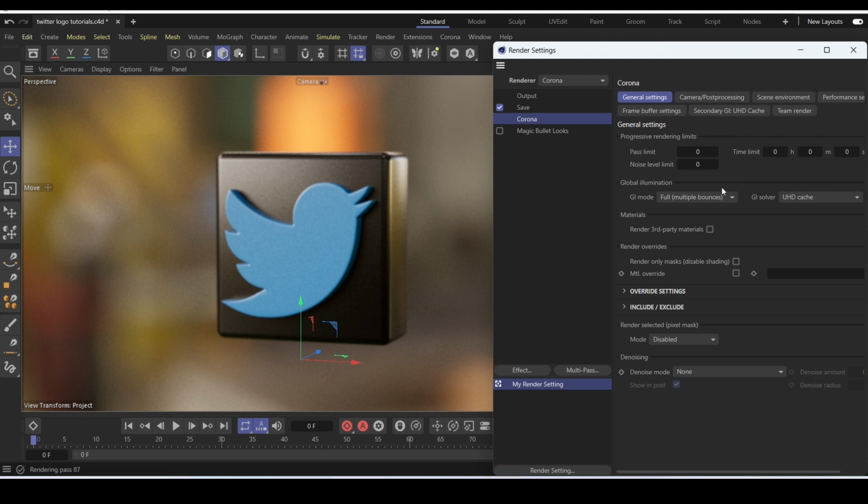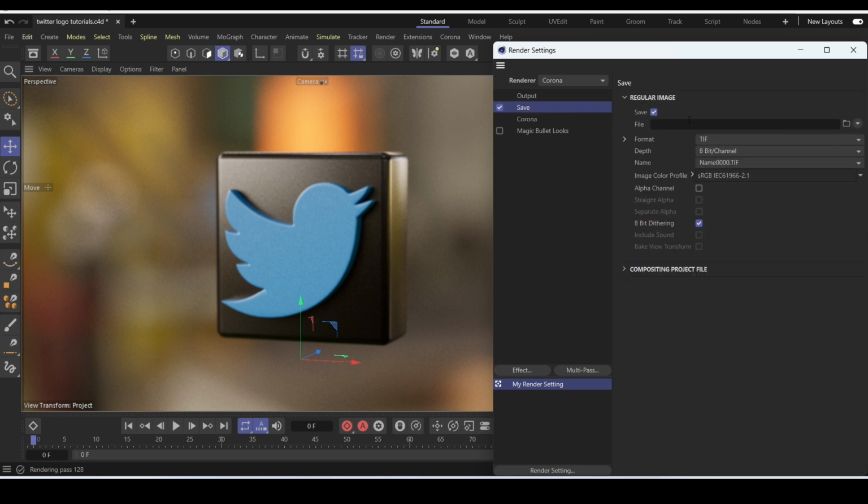So just for this tutorial, set it to like 15, maybe 10, depending on your laptop. We can go all crazy. 10. Set your denoising mode to Intel CPU, unless you know you have a strong graphics card. Then use NVIDIA AI. But use Intel CPU, and select the location you want to save it in.